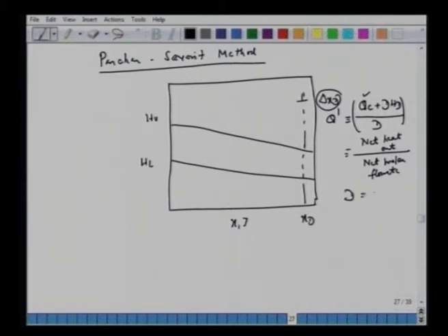Nothing but D, where D equals G_n+1 minus L_n. So at any plate, the vapor flow rate G_n+1 and the liquid leaving L_n, the difference is the same as your top product. So this is the net molar flow rate, net heat out. Of course the stream leaving is D, but we also included the condenser load here in q dash. So we mark this point.